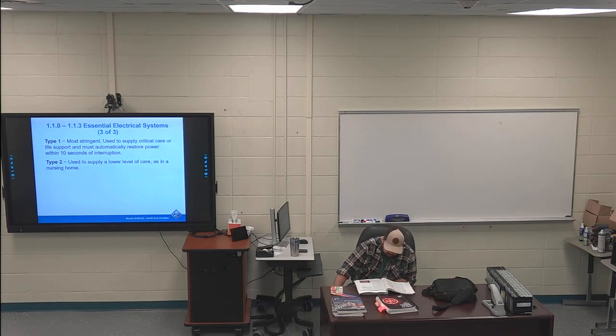120, electrical distribution systems. Second, third, and fourth sentences are highlighted. To ensure continuous electrical service from the utility provider, hospitals and certain other healthcare facilities are placed on a spot network. Spot networks are considered the most reliable and flexible arrangement. Ideally, these feeders are installed in parallel so that a fault in one feeder will not affect or produce faults in the other. So that's saying that hospitals are...